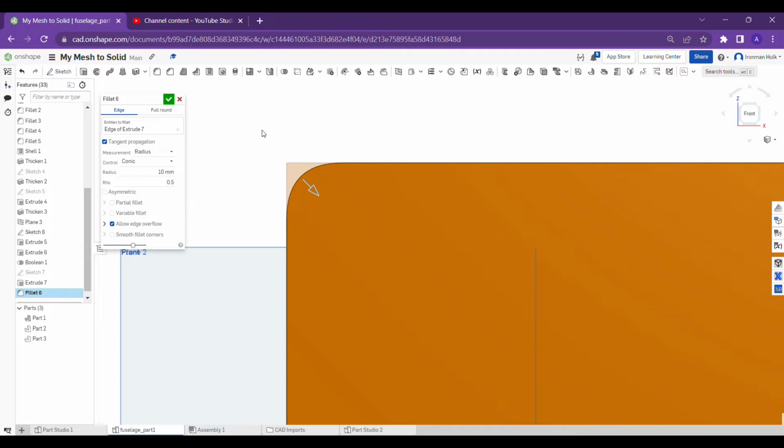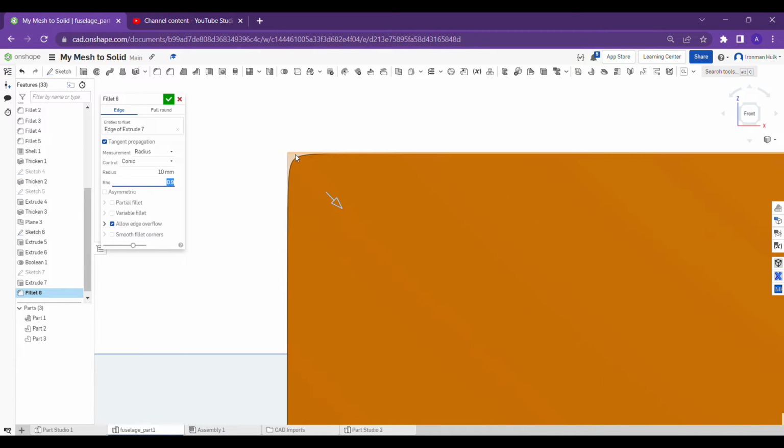And that's the conic, it is different from the normal radius arc. You may already know it if you use the conic arc in the sketch tools. And this is the normal radius we have been using. This conic is like how sharp a curve, how sharp an edge you want for the fillet operation. As I'm giving 0.9, it gives a very sharp curve edge in the fillet operation.